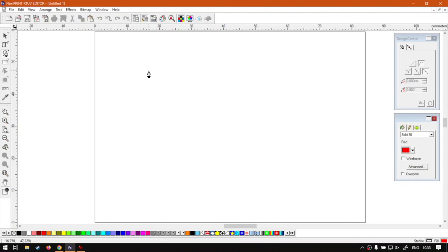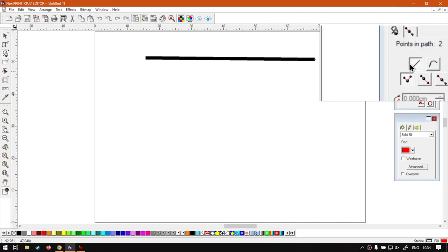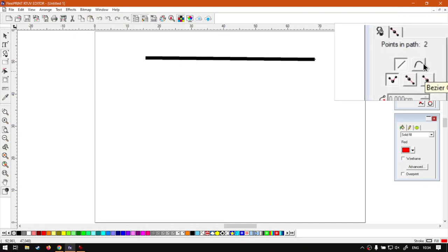Now when it comes to the actual path tool, there's a few variations and different ways we can go about it. So I'm just going to run through the basics so you get an idea of what you can use it for. The first one we have is to basically create straight lines. So if I left click on one point and then I left click on another point, it will create us a line between those 2 points. It's just a basic mathematical equation, as is most vector designs, or I guess all of them. So then this is our first one. We have straight lines. You can also see here on our design central that at the moment it's showing a straight line. Then the next one we have here is the actual Bezier curve.